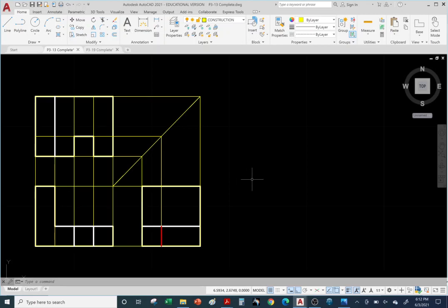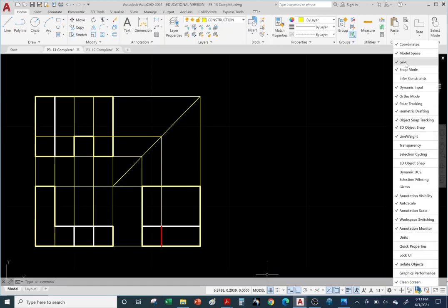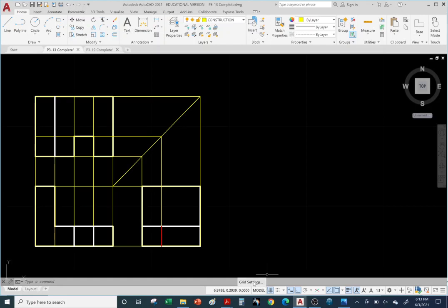All right, so let's say we're ready to start. We're going to create our box, but we need to change the mode. If you go over here to the grid icon and right-click settings, if you don't see this icon, you can always go to the very end, click and turn on the grid icon. Okay, so I'm going to right-click on that grid icon.